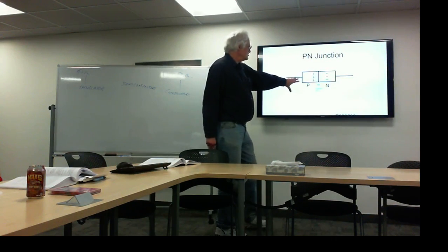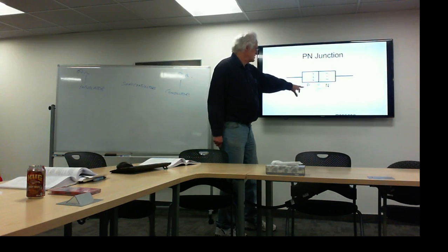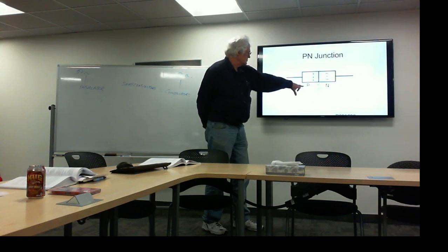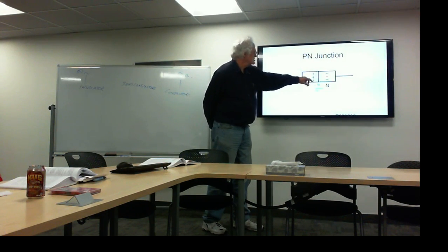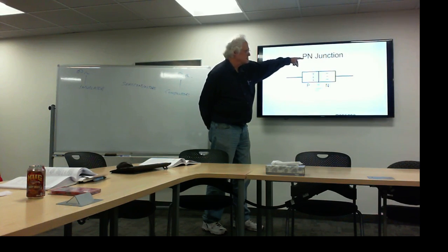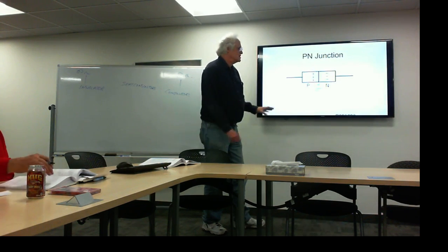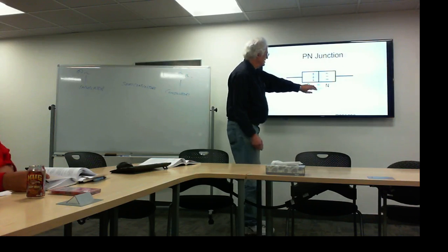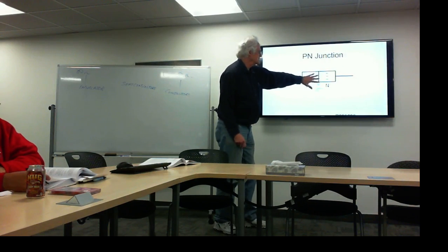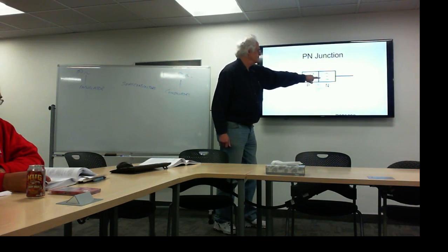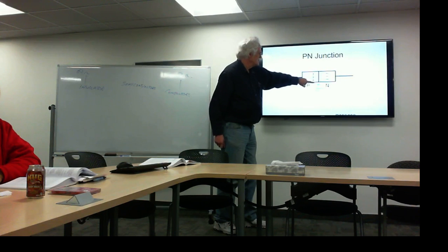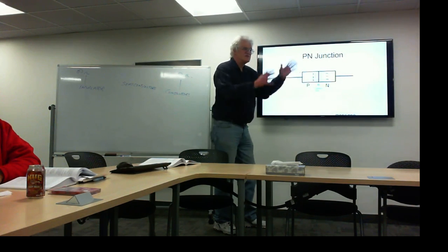So we take two pieces and we're going to combine them. When we join them together, we've got P material, N material, and then there's what we call a PN junction. When we just put them together, in this middle zone, basically any loose electrons will cross over and fill in the holes. So in this middle section, we'll call it the depletion zone. They'll basically have no charge.